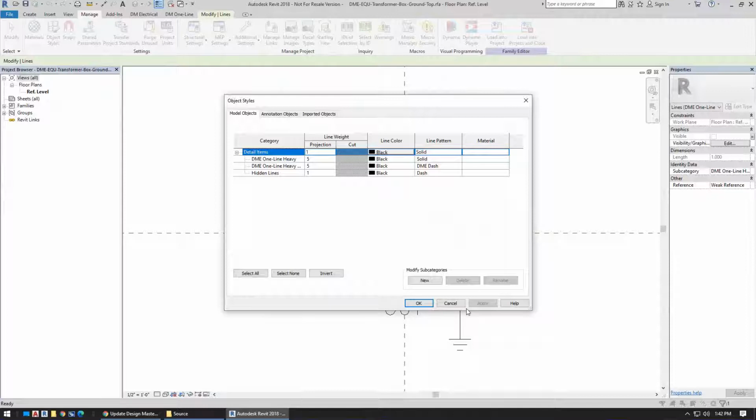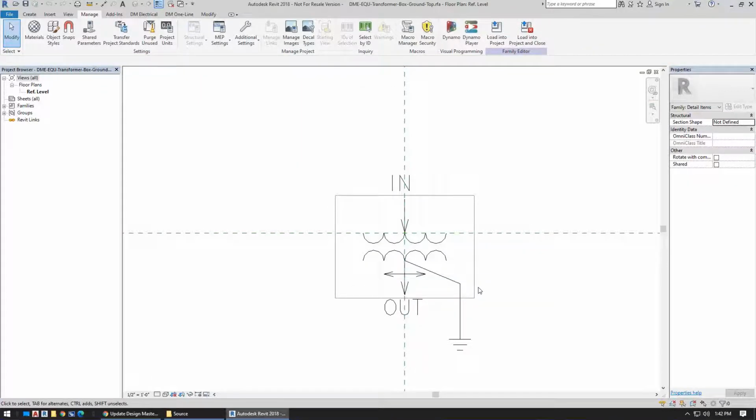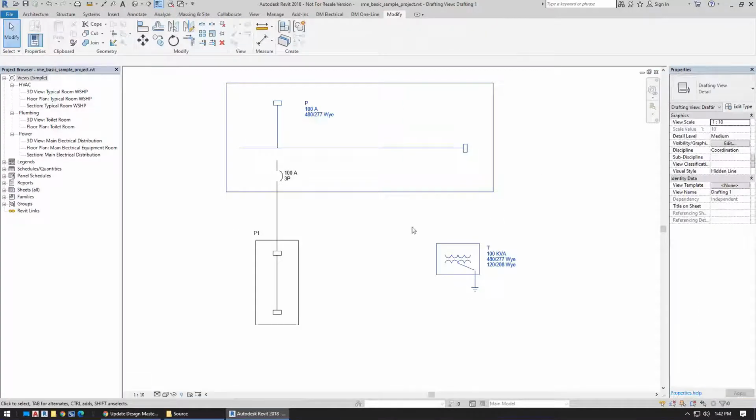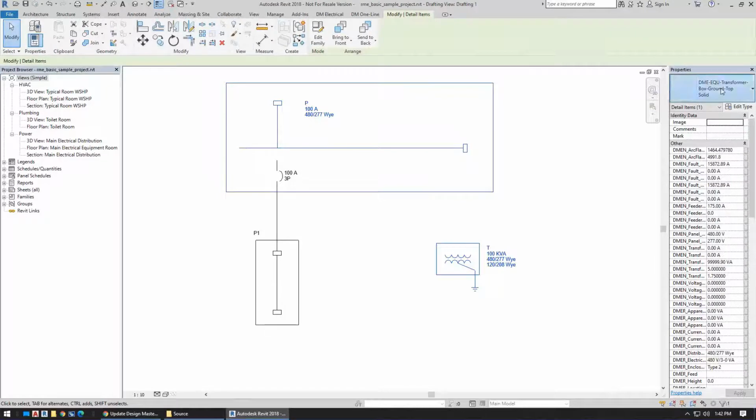That's not a consistent thing, but at least we're using one set of line types in our stuff, and then you can map it to yours. So when your stuff comes in, you might want to adjust the line types in your projects so that they match your plotting standards. We also built ours so that we have a solid and a dashed version of everything, where we control which outside lines are shown, and they have different line types.